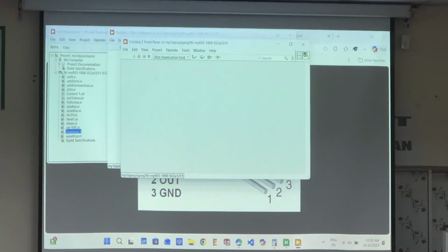Okay, so I'm using analog input 0 here on my hardware. So inside here I have to put the same. Channel A, make sure the channel is also correct. Channel A and analog input 0. I put that. Okay. So now, meaning that I'm reading through my analog input channel A, input 0. AI input 0. Okay? It's done on the initialization. So now I read it, this is the read icon, so I just need to display the result of the value. Put an indicator here. Okay.